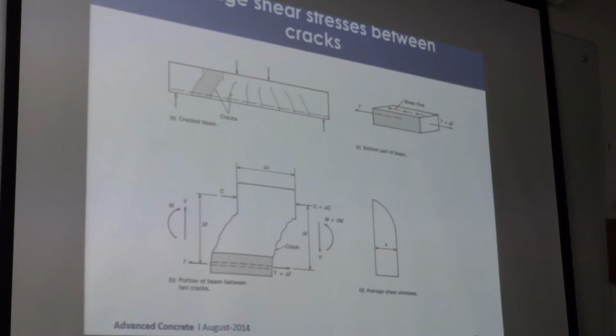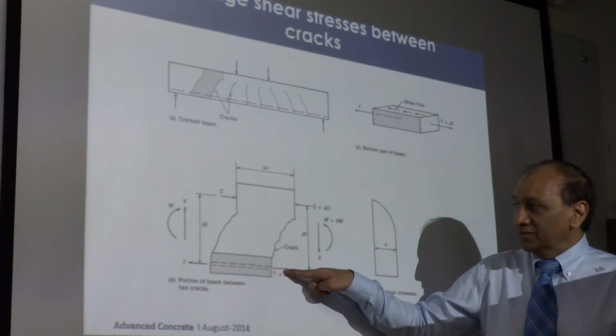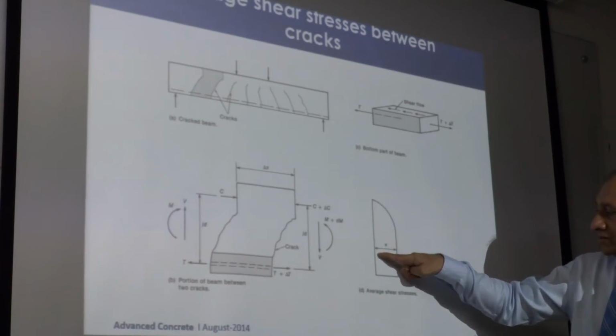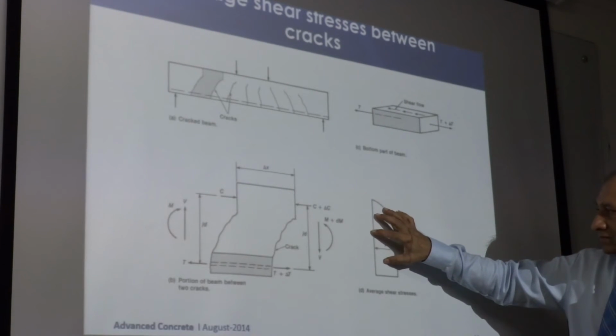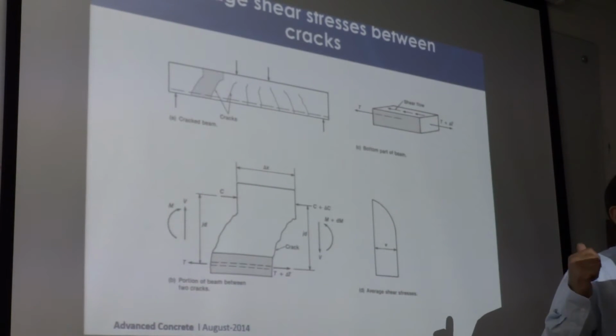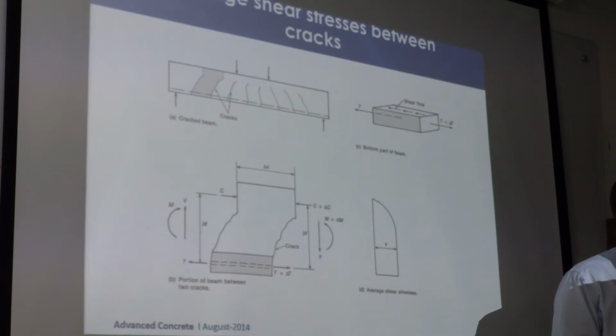The stress is high, so this distribution of the shear stress now changes. It's no longer like we had last time, because of the cracking and because the reinforcement starts to take extra shear at the bottom. This also takes some tension. Because of that, we get this. So we can see that the uniform average stress becomes this, rather than the original one, because of the cracking and because of the presence of reinforcement, which we ignored in our original plots, right?